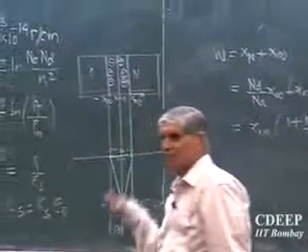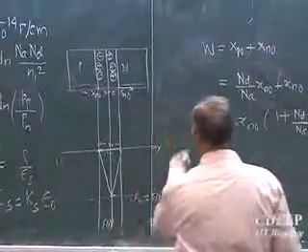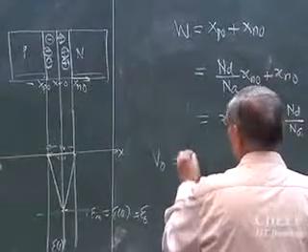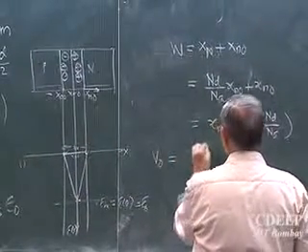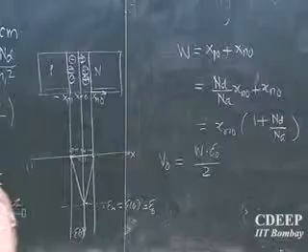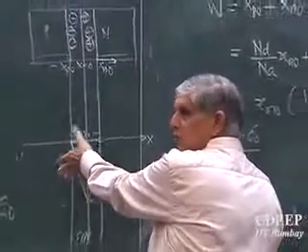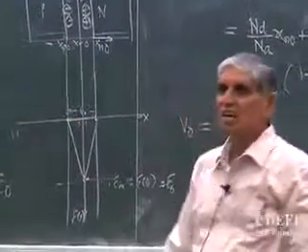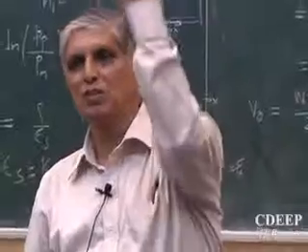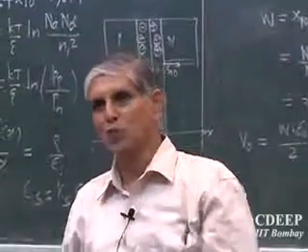If you look at this curve, this triangle, what is the area? What is the area of this curve? That is the voltage across this. Yes, W into E0. Is that clear? Please remember, the area of a triangle is base into height by half. So the integral of Ex from XPO to XNO is nothing but the voltage, which is essentially W into E0 by 2.